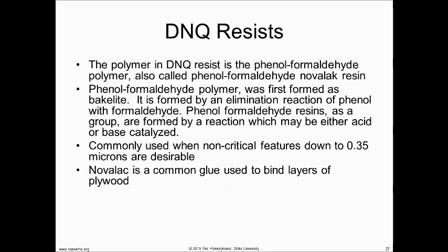If we want to go below that to like 1/10 of a micron, then all of a sudden things are going to escalate into hundreds of thousands of dollars typically. Does that make sense? So beyond 0.3 microns, we start having a need for things like lasers and really more advanced lithography. So kind of in a step in technology, this is my opinion, but I think a lot of people would have the same opinion. I-line is old school and rather inexpensive or rudimentary, but it's impressive as all get out of town. I mean, it's impressive. But in the overall picture, looking at nanotechnology, which is insanely impressive, it's rather rudimentary. Does everybody see that?